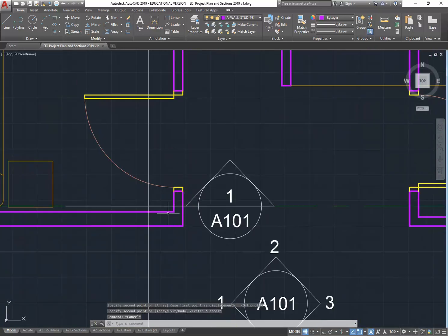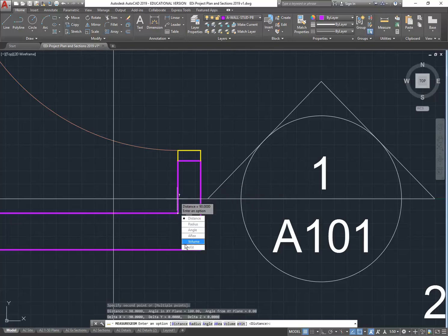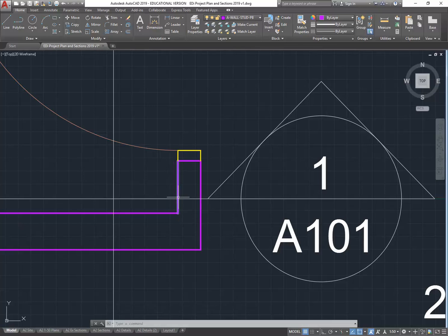And so then, this wall, I should have measured the wall to start with, sorry, but this wall is 90, that's better. Okay, so 90 is more typical for interior stud framed walls. So that means with 10mm lining either side, we're going to have a 70mm stud, and that's fairly typical.